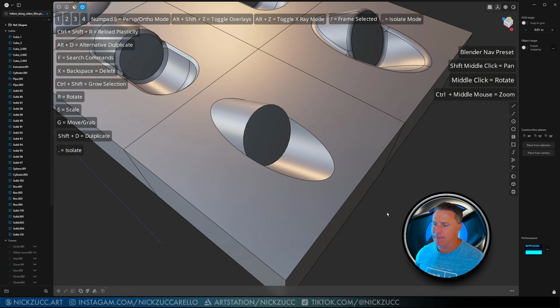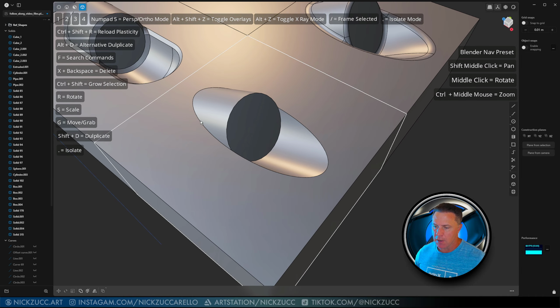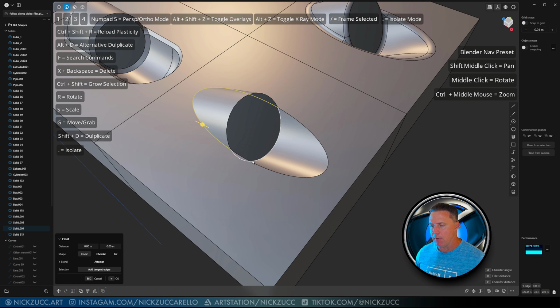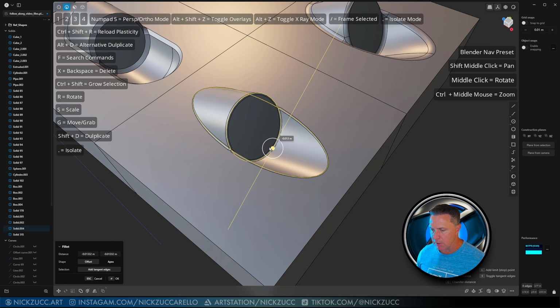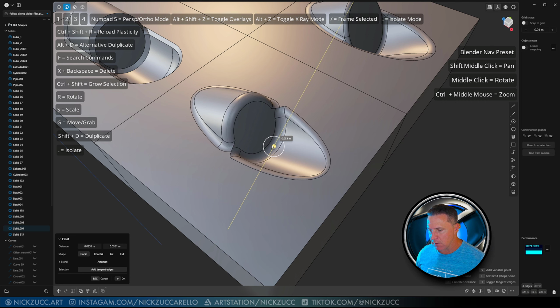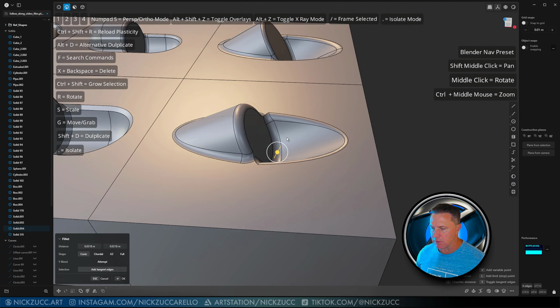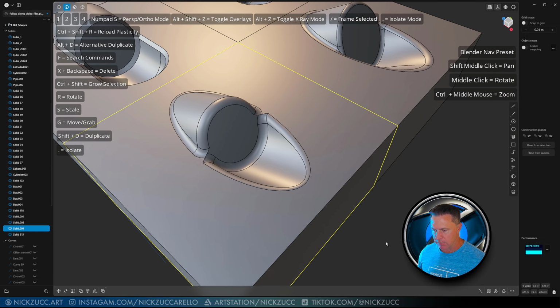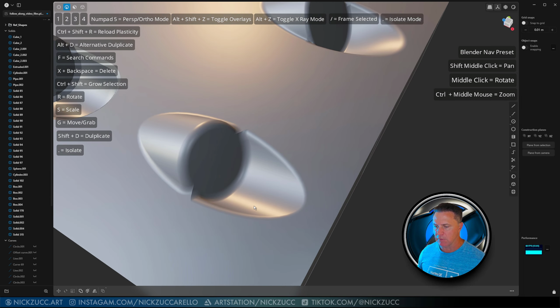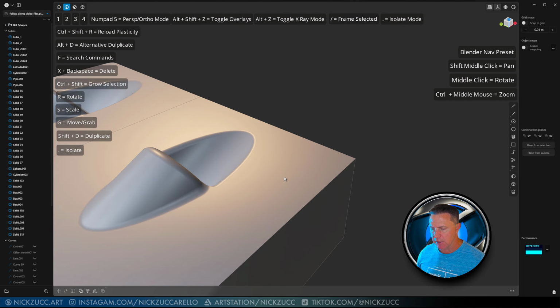And this one will be a little bit more difficult for sure. I'm going to tap 2. I'm going to grab these edges here, here, and here. And I don't have any snapping turned on. I just want to show you what's going to happen in the case of this. So we can't do any chamfer. It is going to give us a fillet, but this is probably not the look that you're going after for this, right? So if I hit Shift Z, you can see we've got this really harsh shading that we've got going on here.